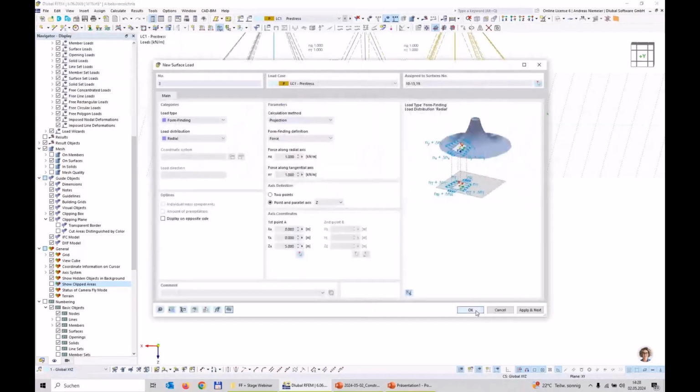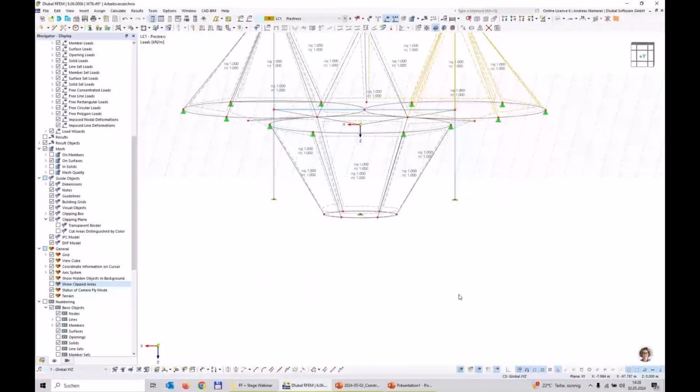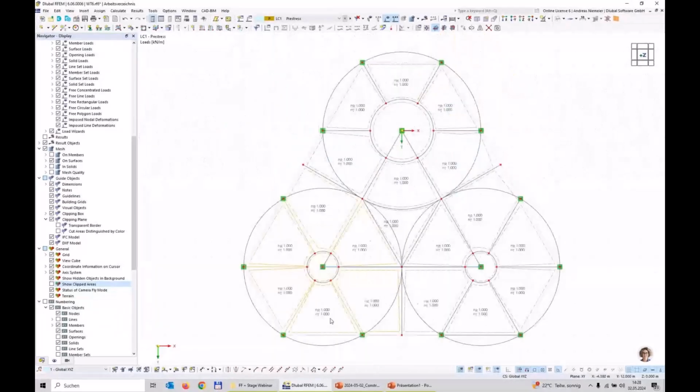Now we specified on every surface part a pre-stress scheme. You see every field is selected, and what is missing is, let's say, the description of the cable. So at the moment the cable only knows I'm running between these green points, but if we hold it straight it will get a really huge force, so a sag would be helpful.